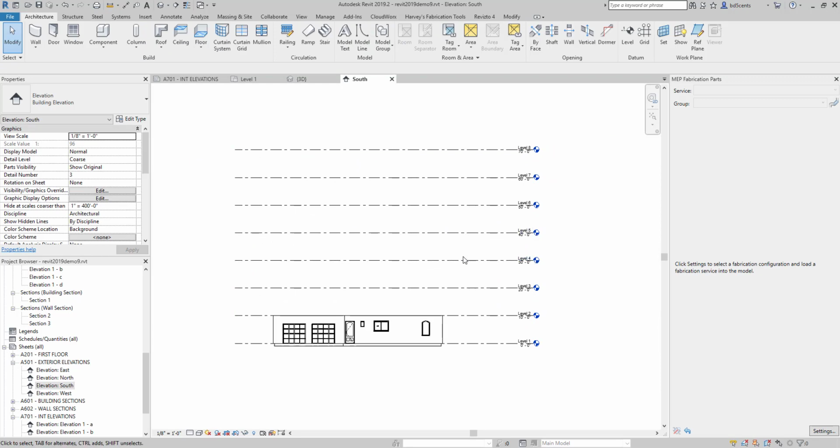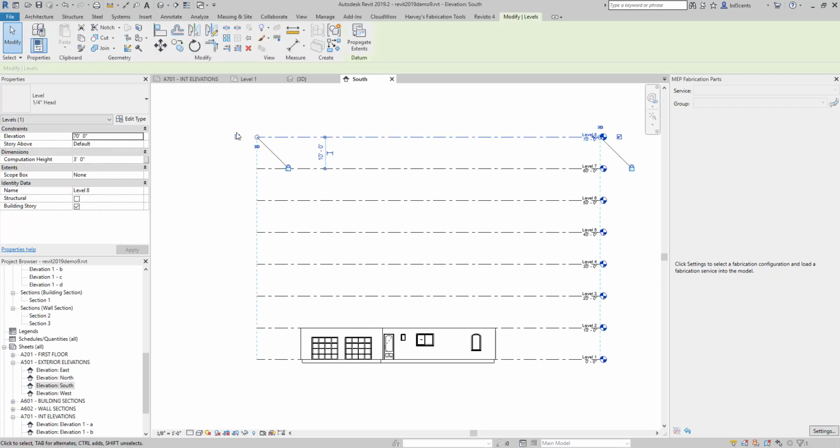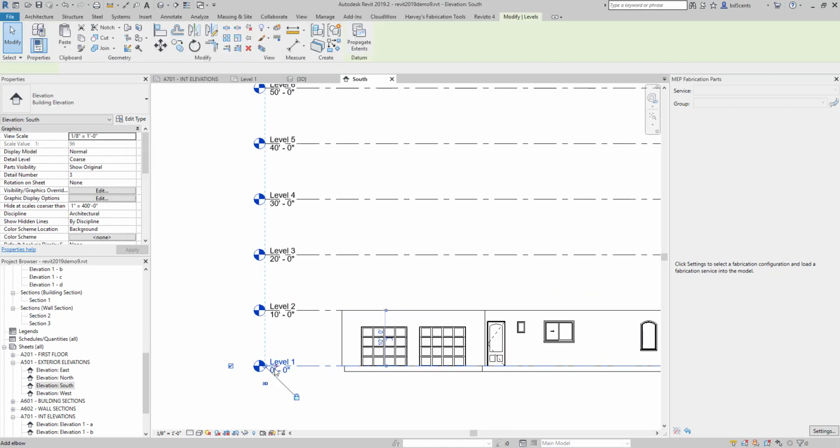That's all in place. We have all of these level markers here, but something that's important is that you can actually turn on the level markers on this side as well by checking these boxes. You could also select all of these simultaneously. You actually can't select all those simultaneously. I thought you'd be able to. Currently, if you check this, it's just turning on the level. So you have to do it one at a time, unfortunately. If you select multiple, it won't allow you to. But if I check that, and check this, now I have my levels showing up on both sides.